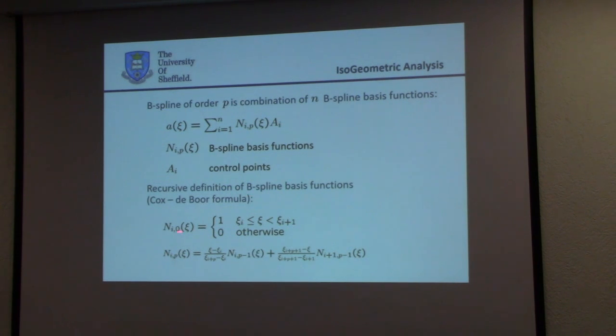So they are defined recursively. So for a simple constant B-spline, it is 1 at a domain and 0 outside. Same as for Lagrangian functions. Then for higher order ones, they are defined recursively. And the B-spline function of I of order P is this interpolation times the one of one order less, plus here for the other node of the order less. Well, for linears, it just gives this behavior, same like Lagrangian. But for quadratic, cubic, it gives different ones.